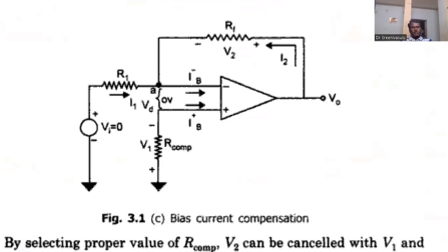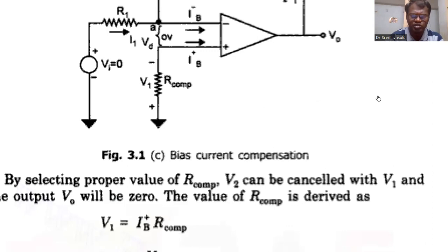You see at a glance again, we are connecting the two input terminals to 0 and we are expecting the output to be 0. But here the input offset current is generated, the difference between the non-inverting current and the inverting current, nothing but IB plus minus IB minus. So it is the general circuit diagram we are going to discuss here.